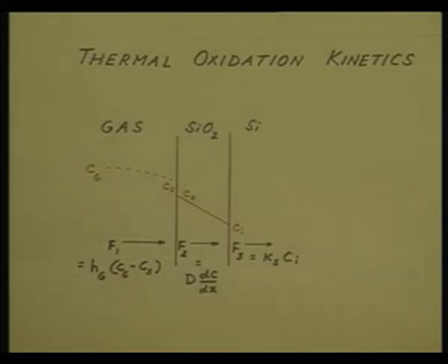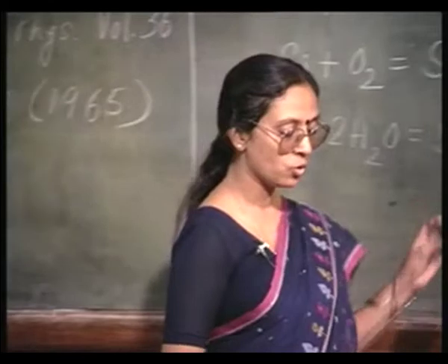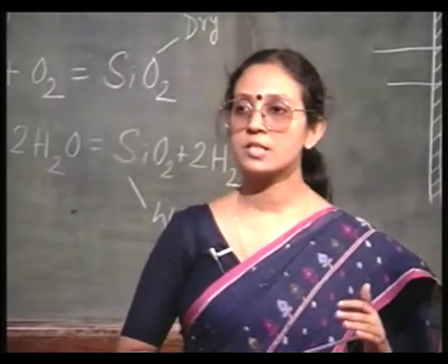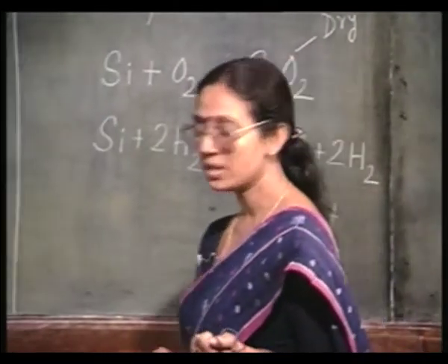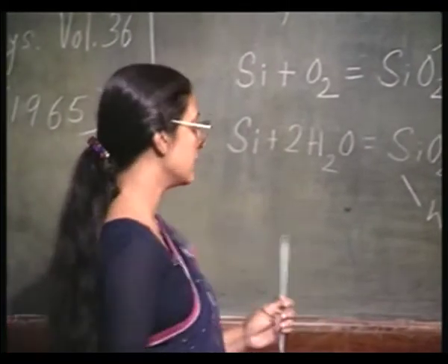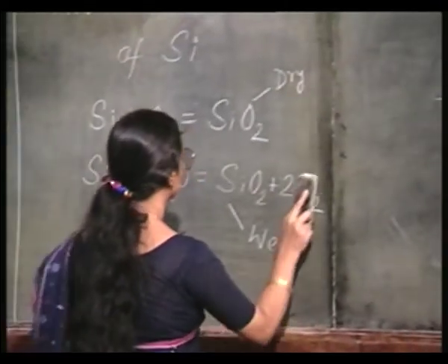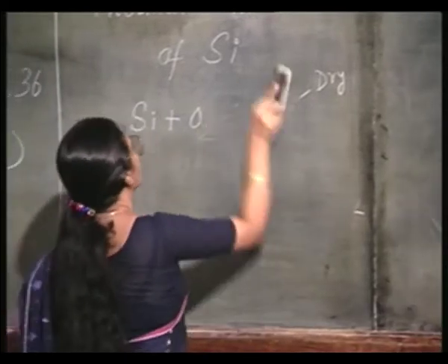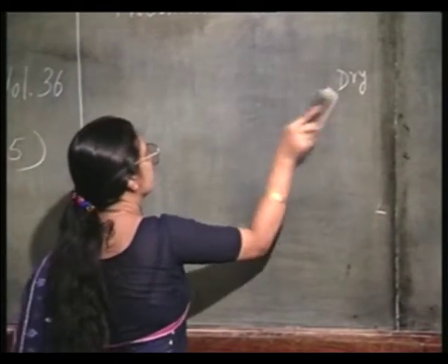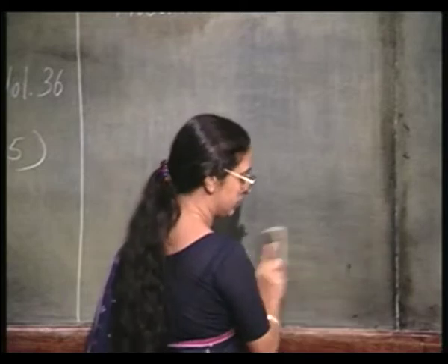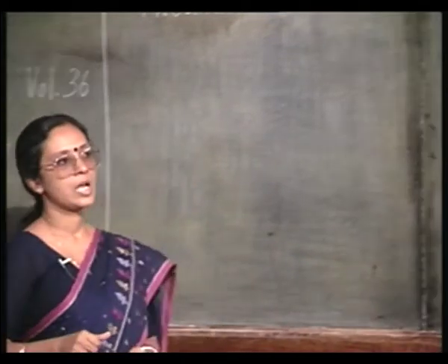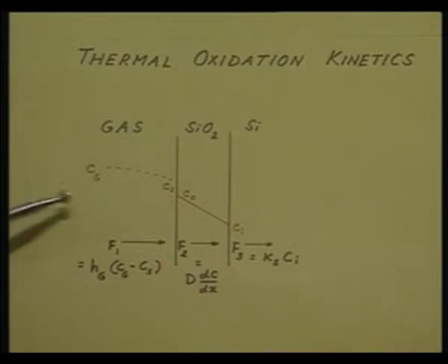Now, let us see what these fluxes are, but before I define them, I have to take note of the concentration of the oxidizing species in the various regions. I have written Cg here.